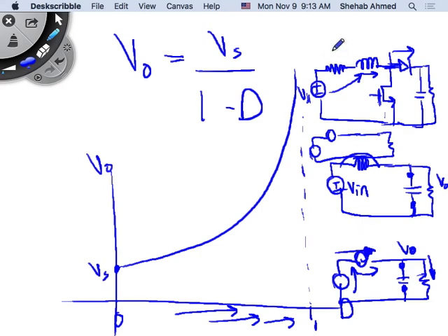If now I consider the value of this loss, anytime I keep increasing the value of current through this resistor, what happens to the voltage drop across the resistance? Increases, right? And it's in an opposite direction than your two sources. So now it's like having three sources, but two sources are summing up, and one is subtracting.